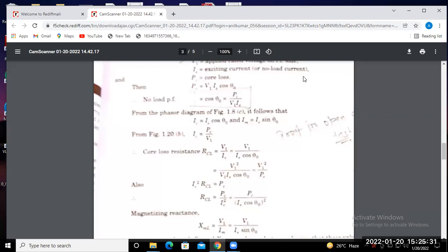What main thing do we have to keep in mind? You have to keep changing the variable point of the auto transformer, and keep an eye on the voltmeter reading. The voltmeter should indicate the rated value of the LV winding of the transformer, whatever the transformer rating on the LV side is. Accordingly, change the auto transformer variable position. Whenever you get the rated voltage of the LV winding through the voltmeter, you stop the movement of the auto transformer variable point.